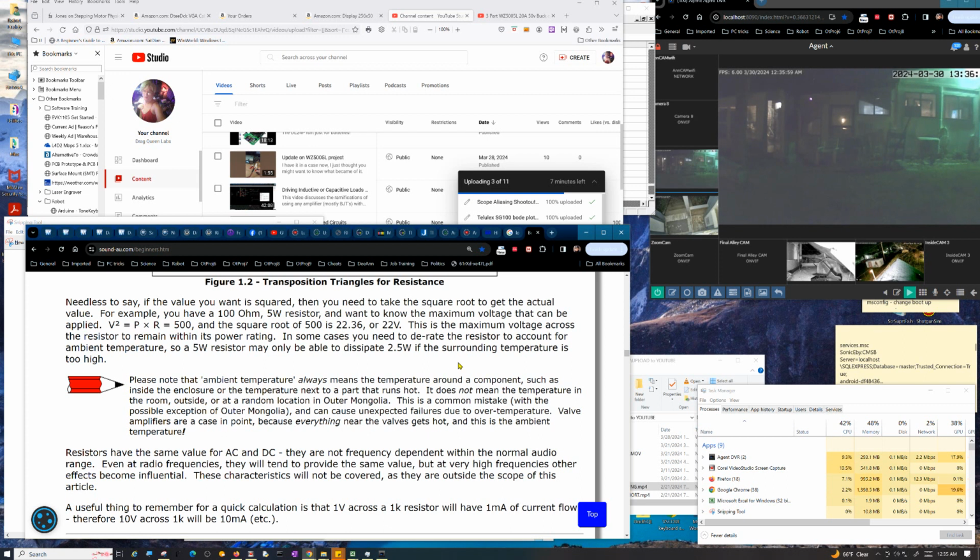Now, you wouldn't want to just take it at a random location inside your enclosure, because that may not be the air that's actually cooling your components. Most enclosures will have dead zones in them, areas that can remain almost isothermal, and might gradually heat up eventually. But that's not the air that's going to directly cool your component. You also wouldn't want to take it at the vent where cool air is being drawn in, because that's still not close enough to the component. That's still relatively cool air that may have to go through 100 circuit boards to get to your component.